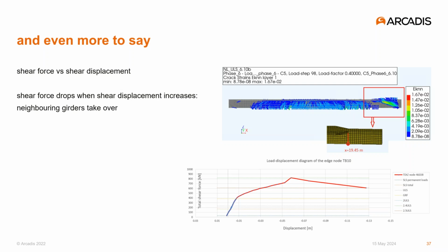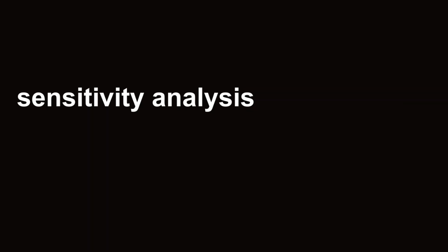It should be said that these load steps didn't converge at all, so the results are not reliable, but the total set of results, so all the pictures of the deformations and the strains and stresses, the total set of results of these steps is still pretty convincing about the actual mechanism. Now we got a clear insight in the behavior and in the failure load and in the mechanism. We wanted to determine the influence of those parameters that we actually knew not too much about.